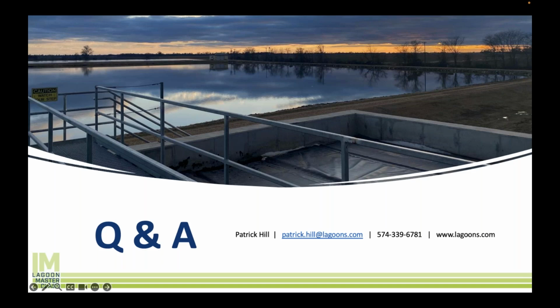One of the benefits of lagoons is you got this really high retention time. So everything that comes in is essentially equalized, right? So if you have 30 days of retention, you're really equalizing 30 days of the influent that's come in. So the reaction rate on BOD removal is high enough and fast enough that reducing it even by half isn't going to make any difference to the overall treatment. In fact, you get better treatment because you're taking the BOD that would have otherwise been discharged and you're sending it back to the front and giving the bugs at the front more food to eat, which then promotes the microbial growth, which then makes it faster because you have more mouths to feed, more bugs, a bigger and more diverse microbial community.